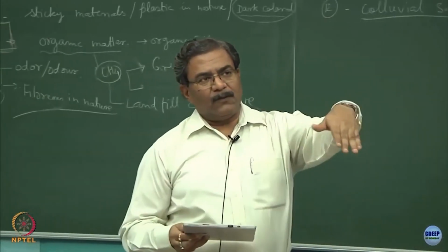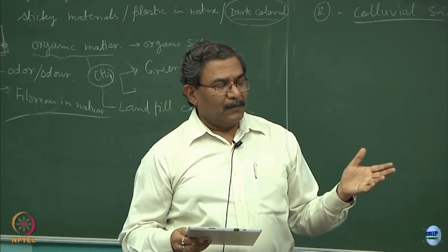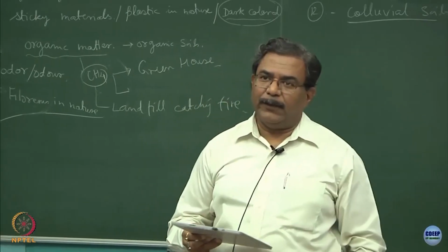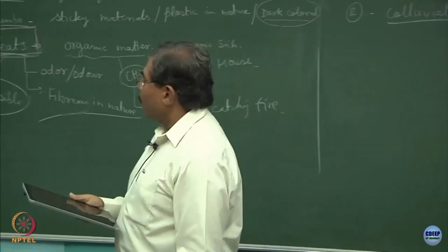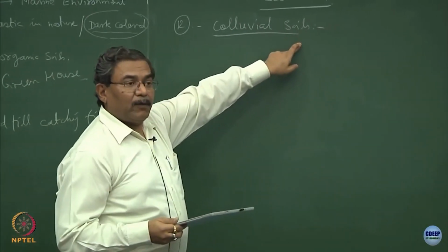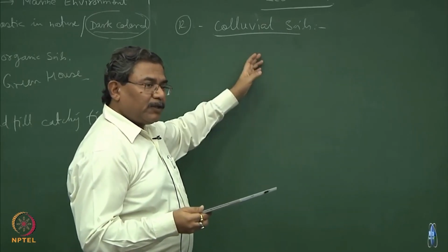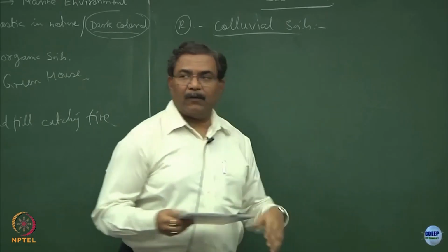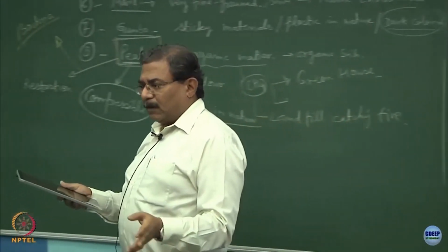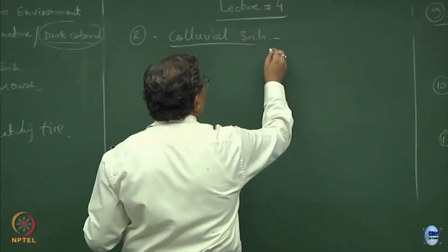So, when you travel through Bombay on Pune Express Highway, Khandala Ghat is very famous for rock debris falling during the rains, is it not? So, we say rain induced slope failures. So, you are right, the colluvial soils are the ones which are formed because of the accumulation of rock mass when they get detached from the parent body, and the parent body is nothing but the rocks, alright, and they get deposited over there. We call them accumulation of rock debris.